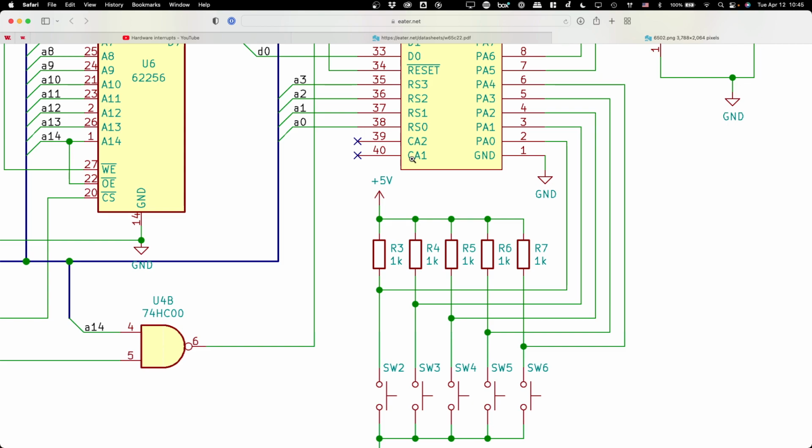So let's suppose that no buttons are pressed and we have AND gates. That means all 5 of these inputs are 1s. And if I AND up a bunch of 1s like this, what do I get? A 1. Let's suppose that button 4 got pressed. Then this would be a 0, and these would all be 1s. Then this would be a 0, that would be a 1. This would be a 0, this would be a 1, and the output would be a 0. So cascading zeros. If any button gets pressed, this is going to flip to a 0.